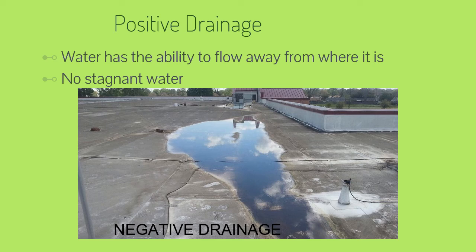In doing site grading, there is what we call positive drainage and negative drainage. Negative drainage is where water stands still on a place. That is not what we want on our site, especially on parking areas, play courts, or other open spaces where a volume of public will congregate. We need to be doing the positive drainage in site grading. So what is positive drainage? Positive drainage is water that has ability to flow away from the site, or there should not be any stagnant water remaining in the regraded site.